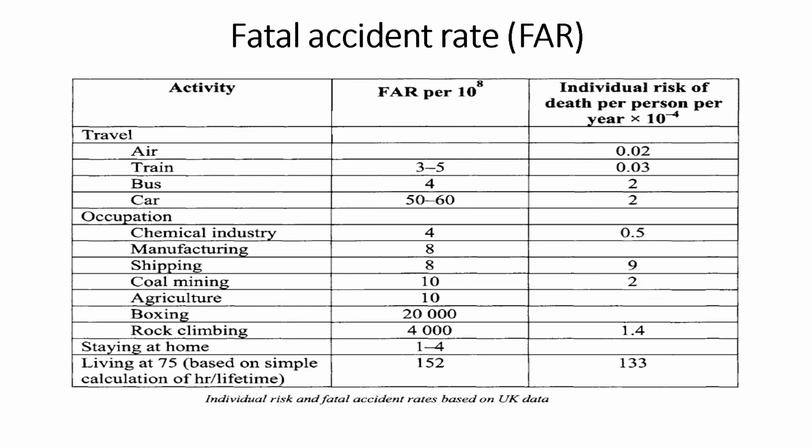Fatal accident rate, or FAR, is a method of establishing a tolerable level of risk. If a design team is prepared to define what is considered a target fatality rate for a particular situation, it's possible to define a numerical value for the tolerable risk. The generally accepted basis for setting the FAR figure is the number of deaths per 100 million hours of exposure.